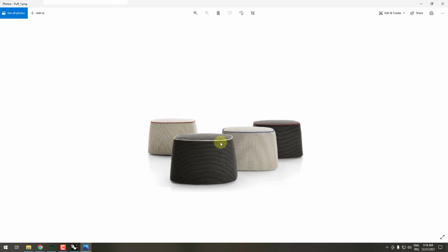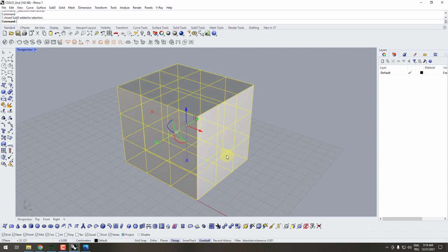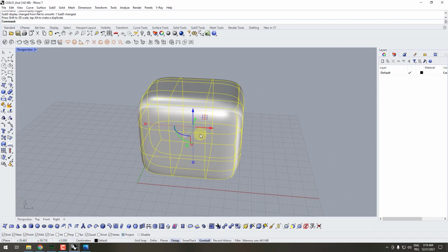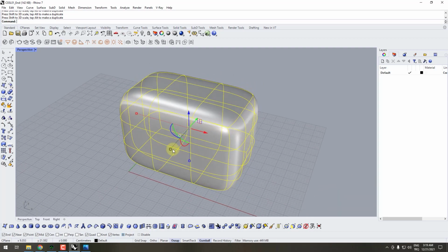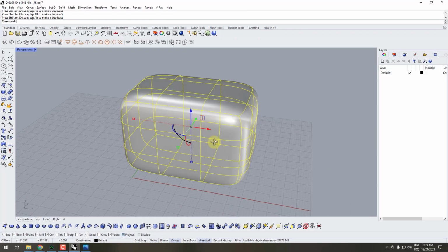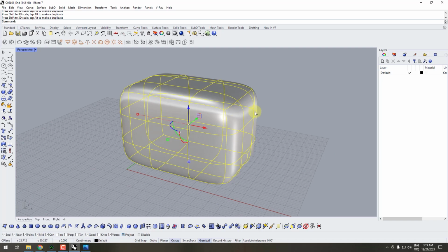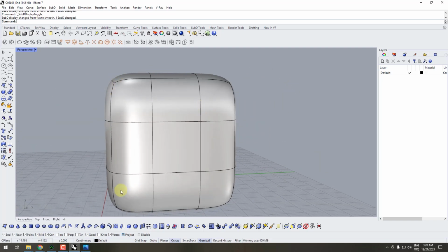My geometry is a little bit narrower than this path, and the upper side is narrower than the bottom side of this path. We can do these adjustments by playing with our vertices. In SubD mode, I'm selecting my box and playing with the geometry using my gumball and trying to get the general proportions right. When I'm happy with the general proportions of the model, I will try to adjust smoothings at the edges. Right now, these smoothing amounts are too much for my model.